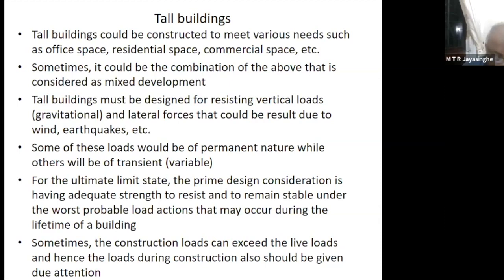So even the minute savings are so important. So that's why we say in tall buildings, don't change in 25 millimeter intervals, change in 10 millimeter intervals. So the slab can be 140 millimeter, 150 millimeter, 160 millimeter, 170 millimeter, 180 millimeter, 190 millimeter, or 200. Don't change the slab thickness in 25 millimeter intervals, because in a tall building, even such a change may be too much. The reason is we need very much optimized structures.